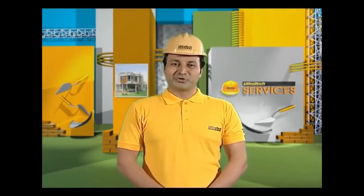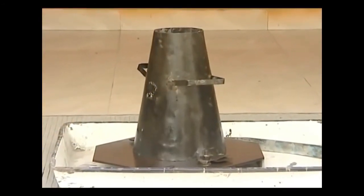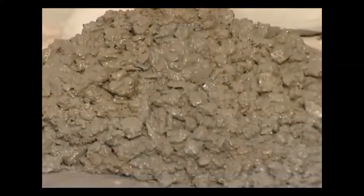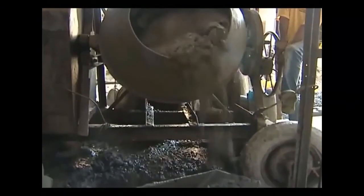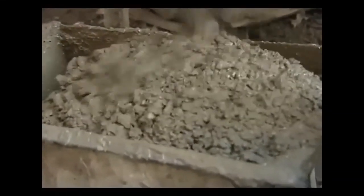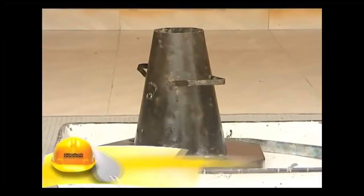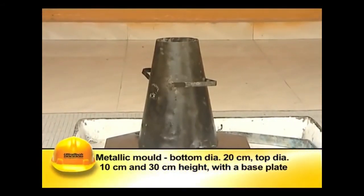Let me show you the procedure. Slump cone test is a simple and popular test extensively used at sites to assess the workability of the concrete mix. The test should be conducted at the commencement of the concreting operations or whenever the workability of the concrete changes. The apparatus for conducting the slump test essentially consists of a metallic mold in the form of a frustum of a cone with a base plate.